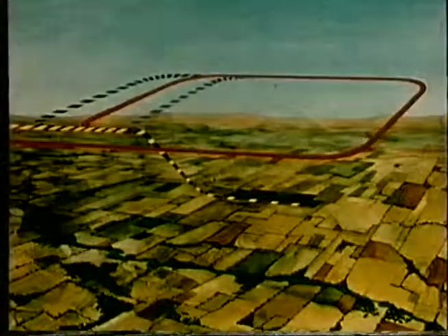An aircraft landing, or in the final stages of an approach to land, shall normally have priority over an aircraft intending to take off. However, an aerodrome controller must judge the position of an arriving aircraft and determine whether he can clear a departing aircraft for takeoff without infringing the aerodrome separation minimum. An aircraft shall not normally be permitted to cross the beginning of the runway on its final approach until the preceding departing aircraft has crossed the opposite end of the runway or has started a turn, or until all preceding aircraft are clear of the runway.